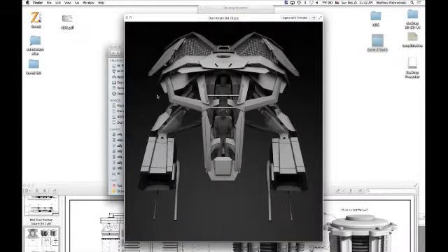And the Bat, which was a large-scale model, about 3 feet long, that was fabricated for the design process. Then I used photogrammetry software to photograph it, and using multiple camera angles in the software, I was able to pull points off in 3D. Those I then imported into Form Z to create all the surfaces and make everything nice and flat and true, because as with any LiDAR scan or point import, reality, things are not very square and true.